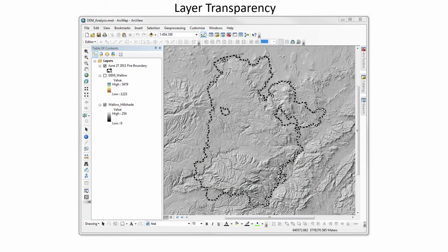Now I like layer transparency. This is a neat layer quality, another set of instructions on how to draw. It's fun to play with and can be really helpful for making sophisticated maps. Now, for example, maybe we want to illustrate the topography of the landscape. This that we see here is called a hillshade. A hillshade does really well for showing topography. We can see where hills are, we can see where ridges, where drainages go. Downside of it is it doesn't really differentiate between high and low elevations very well.